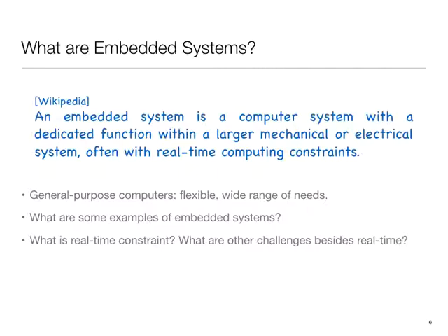In some cases, there is absolutely no laxity in this. That is, if you miss, the system has essentially failed, in which case the term which is often used is hard real time. But most systems are not entirely hard real time. There is some degree of slack that does exist, and so the other term which is used is soft real time.